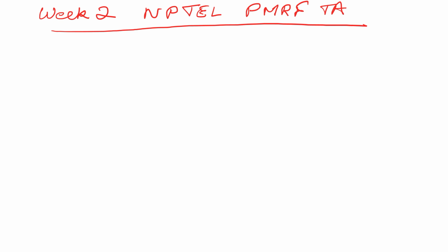So coming over to the contents of the second week of this course. We have started out with the calculation of configuration entropy, and we have seen how in a binary mixture of solid solutions, an addition of a solute to a solvent increases the configuration entropy and hence causes reduction in the free energy of mixing. We'll be going ahead and reviewing the concepts that have been covered in the past 4 or 5 lectures in the past week.